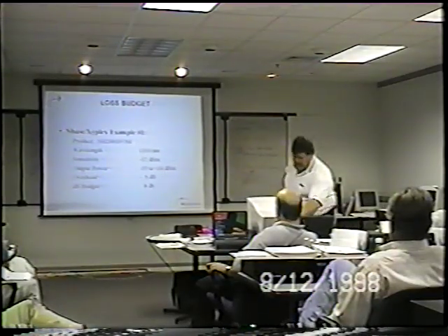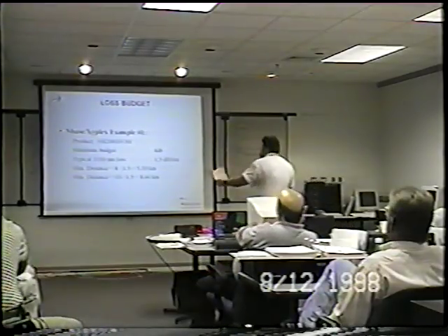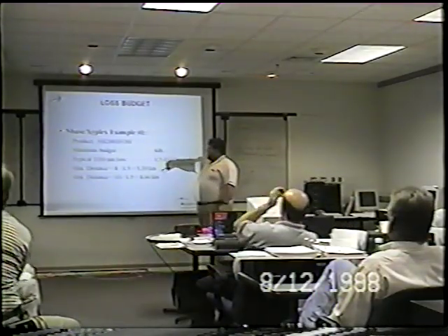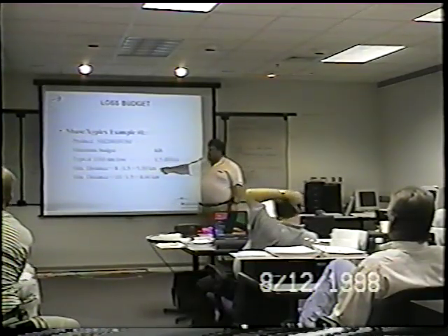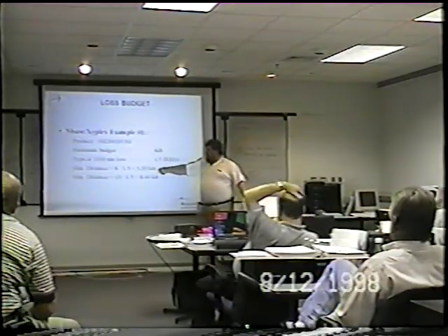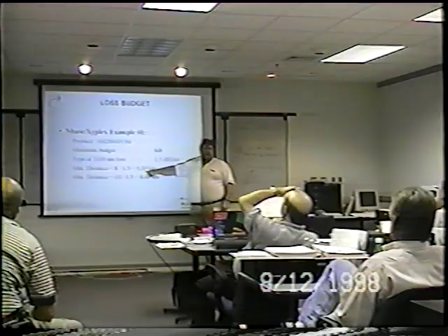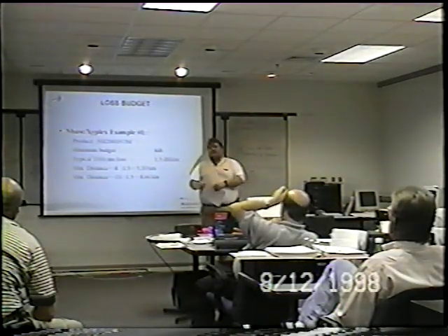Okay, so let's look at the results of that. We'll take that 8 dB. The typical link loss for fiber at 1310 nanometers is 1.5 dB per kilometer. Based on the low-edge power output, the minimum distance, I'm easily going to do 5 kilometers end to end.